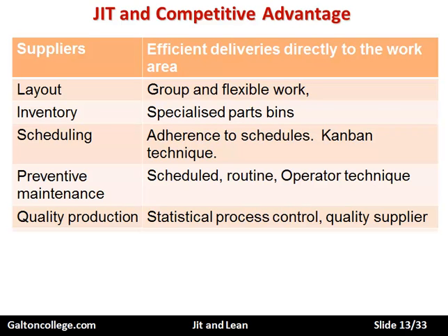And quality production. There should be statistical process control and good checks on quality. Sometimes the workers are the best source of quality information. Workers know what the parts are, and they know what the dimensions of the parts are, and the workers can keep an eye on it. They're involved at each step. So as the work moves through the various stages of production, the work has been monitored by the operator at that level.